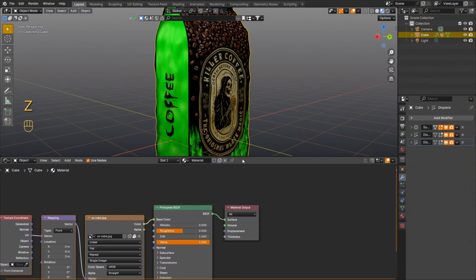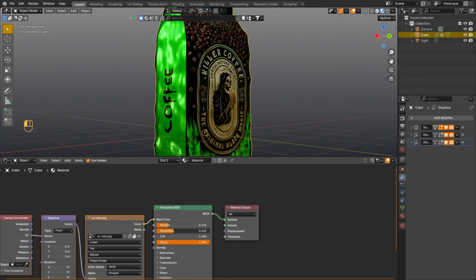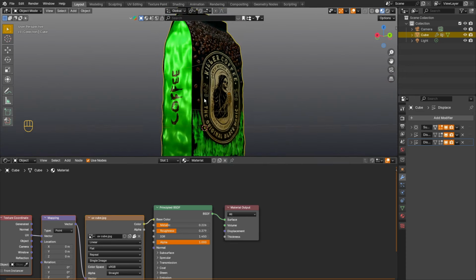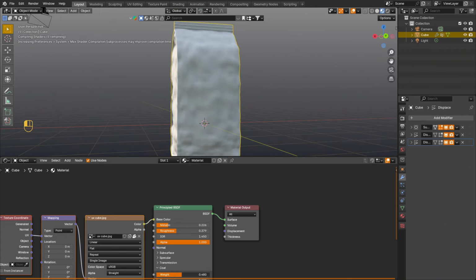And so, now, I want to slightly adjust the material from which the packaging is made. Usually it is slightly similar to oilcloth. Therefore it should glare. To create this effect I lower the roughness slightly, and also increase the weight of coat to approximately 0.25.